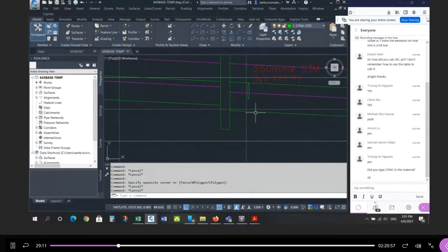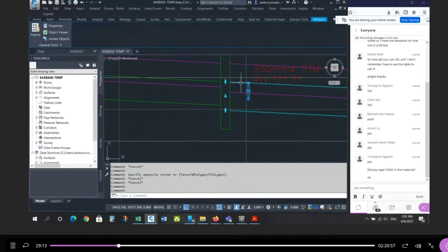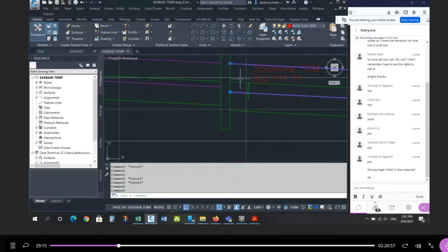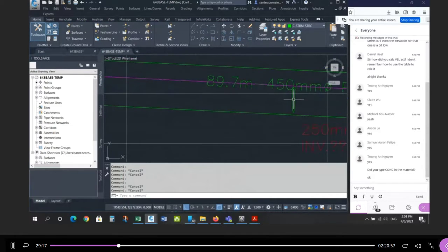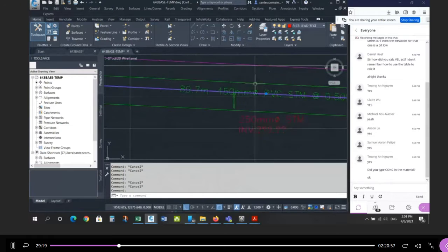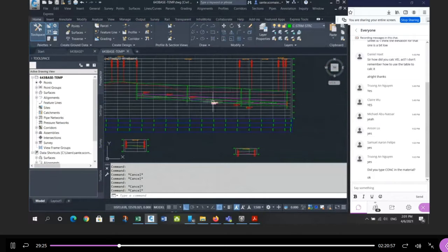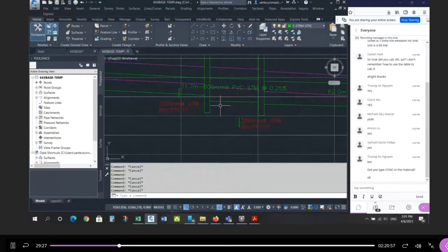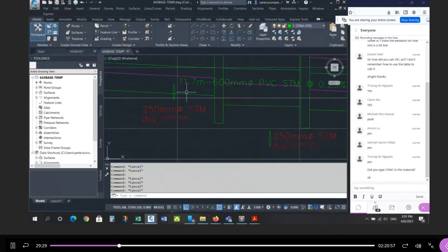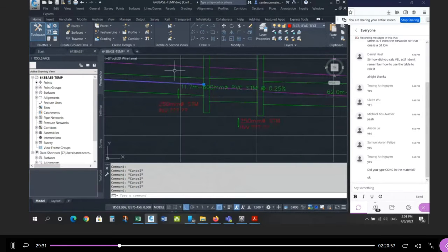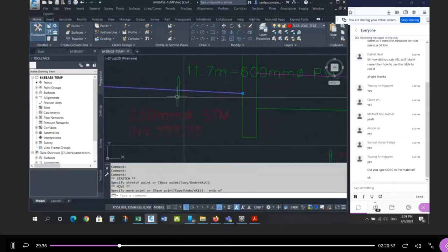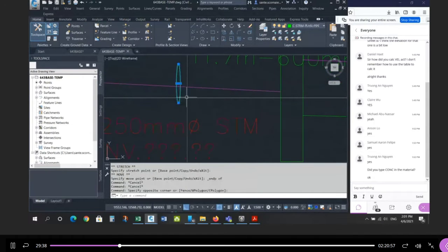The next one, I've resolved that one as well. Now it's inside the pipe instead of below this pipe. So that one works. The next one used to be below the pipe. I'm just drawing this for reference, and now it's inside the pipe, so that's good. So I've resolved 1, 2, 3. The next 2 are still no good. Here's where the pipe went. It used to be up here, and I shifted it. It's now down here. It's better, but it's still too high. This is still too high.